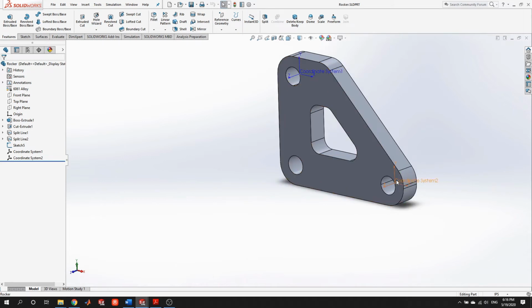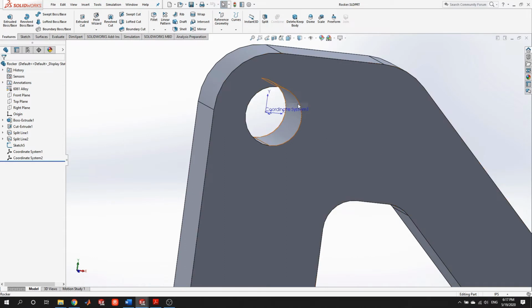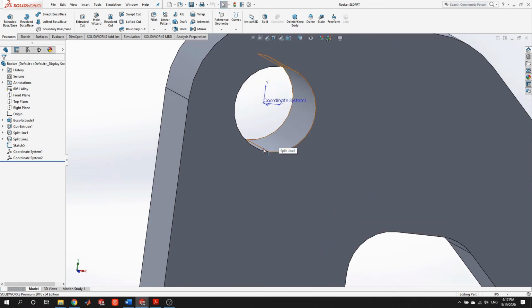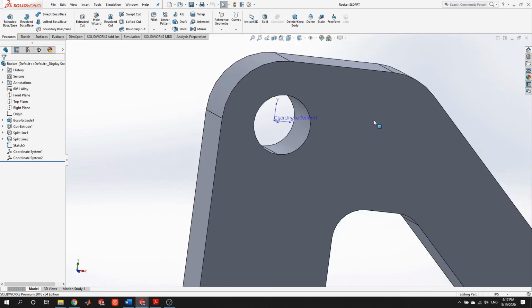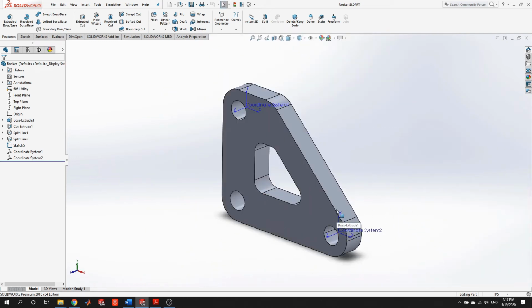Also, I've put in these coordinate systems, these reference coordinate systems, so that we can apply what's called a bearing load here to give an even better representation of applying a load where near the edges, since it's tangent, it's really not carrying any load. So the load varies as it moves along the face, having really the maximum here in the center, again, to give a little bit more realistic physical scenario.